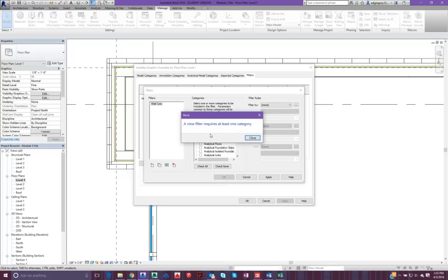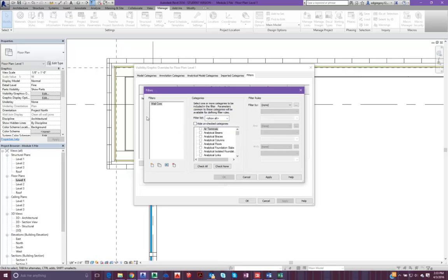Let's make another one. Let's go down to Parts. I struggle with this for a little bit, so if you get a little bit confused, I completely understand. And you can filter by the material. Equals, and we're going to want to make this metal stud layer, because that's the core of your wall. And we'll hit apply.